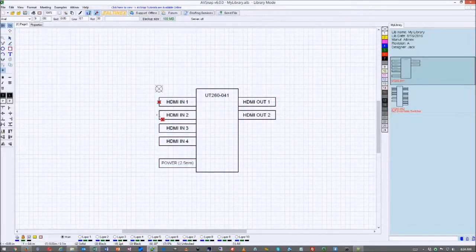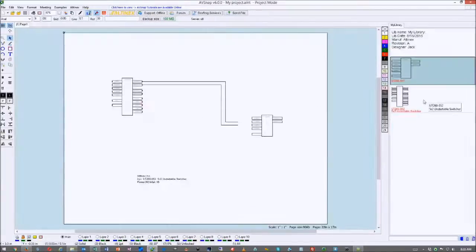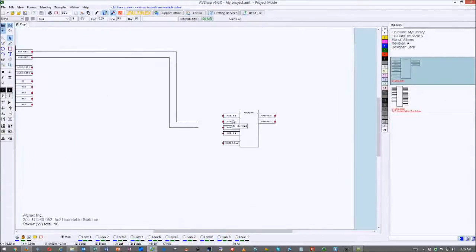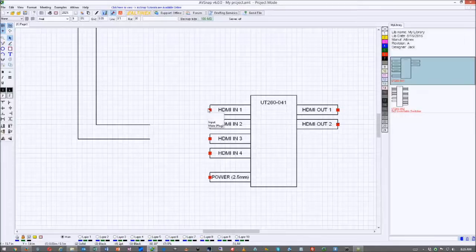We already know how to adjust the snap points and add different functionality. I'm just going to add the snap points here. And I'm going to save this by pressing Control-S. Okay? Now, right here, there's a function, return to a project. And when you return to project, that means that you saved your project, you were in the project, you went to the library. When you return, you're going to be right in the same place where you were before, except now the symbol is automatically adjusted.